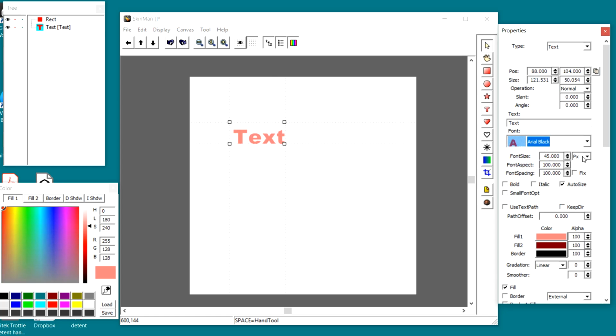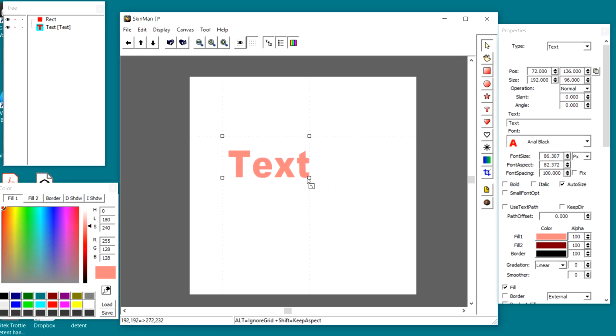And then we have the ability to change not only the size, we can do that by dragging the corners. Or we can change the aspect ratio, and the size by just dragging it around. But you can also do it mathematically. And if you want to keep the fonts to be kind of an even size, it's like 100.1692. Let's just call it 100. And the aspect ratio, I tend to do it with the mouse wheel, which gives me a nice even number here. I'll change that to 65.